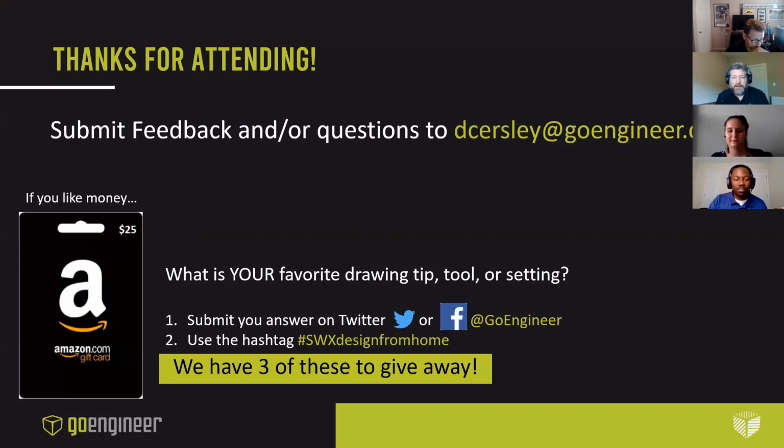Theme for a black viewport. So we've got options for the different colored themes. Avinash is asking about the black. That's kind of an AutoCAD kind of thing. You could do it at the drawing level, maybe easier, but at the sketch level we've got blue lines, red lines, black lines, yellow lines. Black lines don't show up on a black background. So I've seen people who do want a black background have to change a lot of the black colors over to white or some other color and swap them around a little bit.